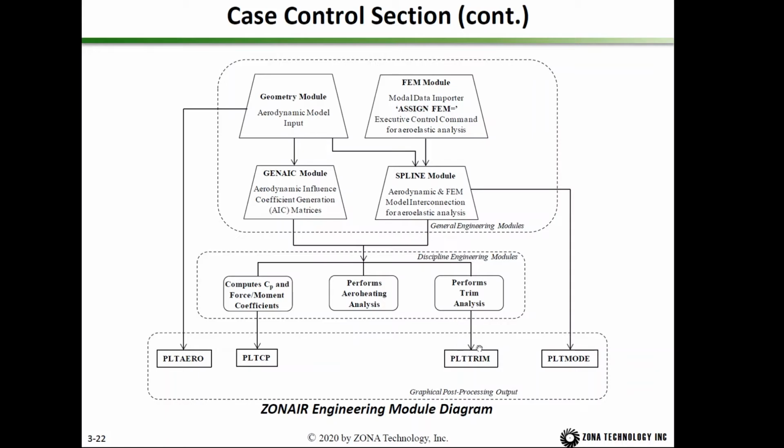You can use the PLOT TRIM card to look at the deformed aerodynamic model under the trim loads. And the spline module can output the spline mode shape on the aerodynamic model. You can look at those mode shapes on the aerodynamic model using the PLOT MODE card.